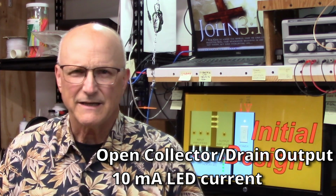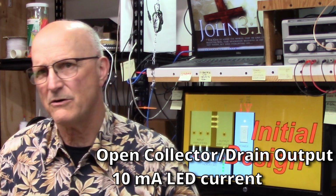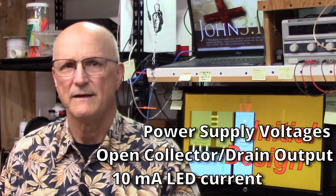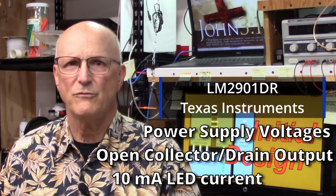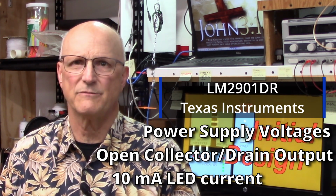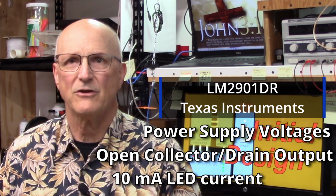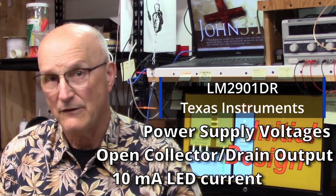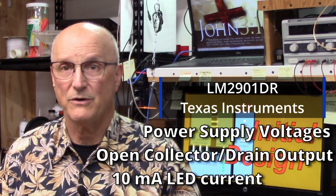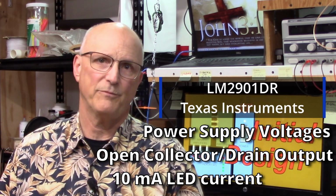Then lastly, we want to be sure that the comparator can handle the power supply voltages that I will be using. I ended up with an LM2901DR from Texas Instruments. This can handle up to 38 volts, so the LEDs connected to the plus 12 volt input won't bother it when the output goes to its high impedance state.